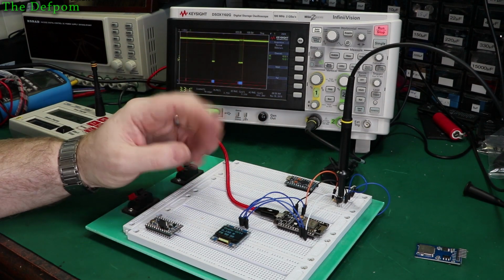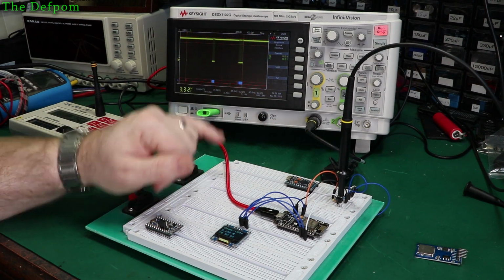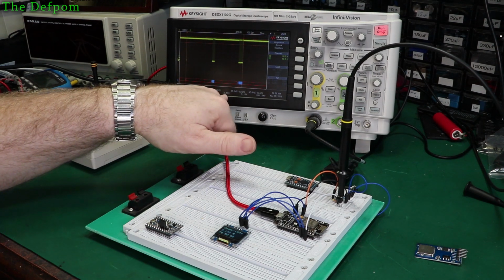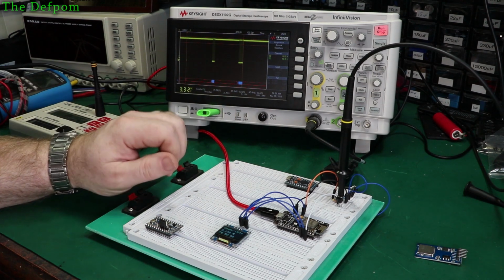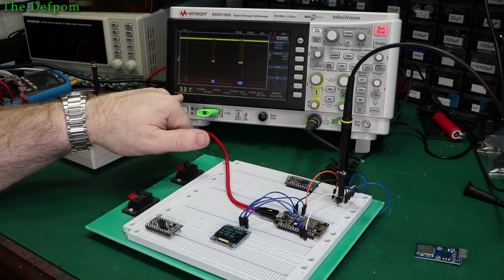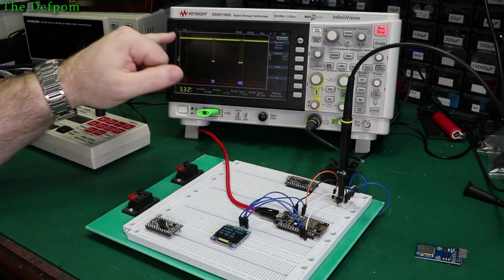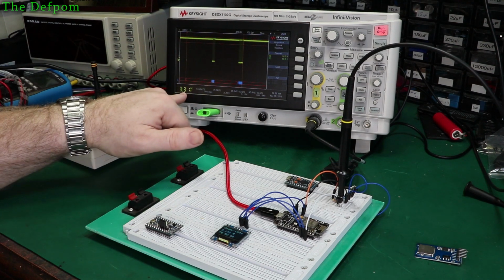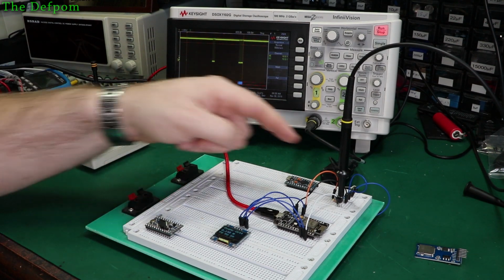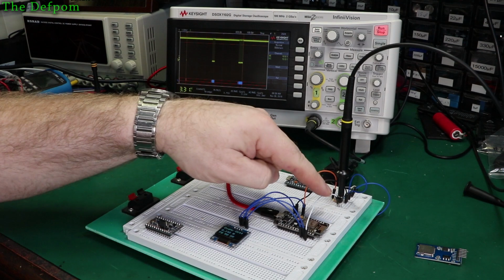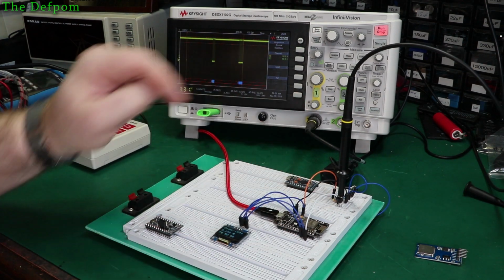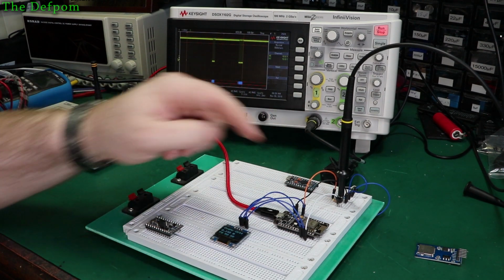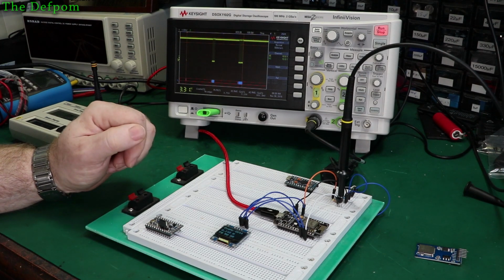Again, that's basically how they work. I'm getting a slightly different voltage here, 3.7 volts peak to peak, but it's reading 3.3 volts on the actual supply rail, because I say it's normally high. Right now it's in a high state, which is why it's reading 3.3 volts here. That's the actual output going to this. You can see that conversion box there is going from 5 volts down to 3.3 volts to supply the ESP8266. It should all be fine, really.